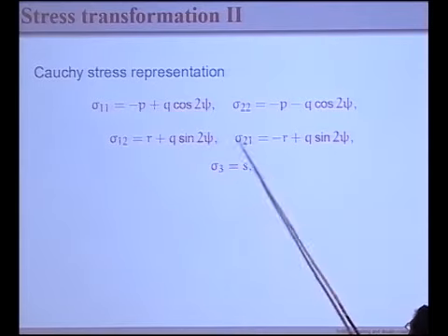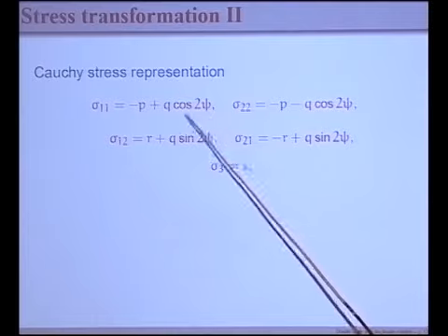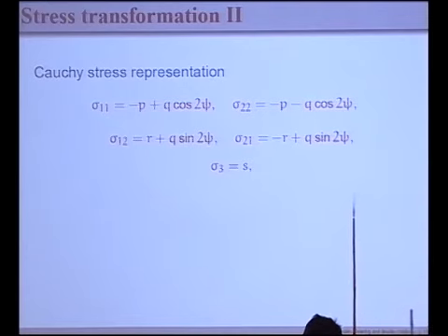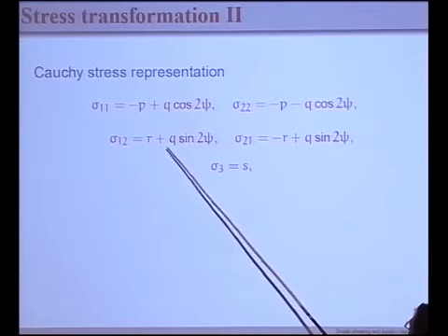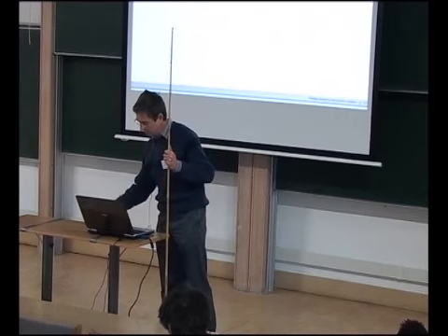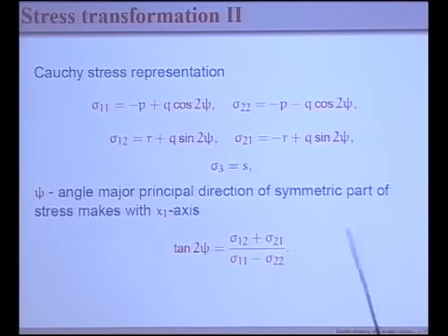If we're familiar with the stress representation which comes on the next transparency, we can see that with the difference the P's disappear, and with the sum the R's disappear, which gives a very useful and very simple representation for the stresses. So in this general state of stress, we can have this representation here. This is a very common thing to do with the double shearing model. Tony Spencer always used this kind of representation, although in his case R would always be 0 and S was also absent. But this will work for any yield condition, not just the Mohr-Coulomb type.